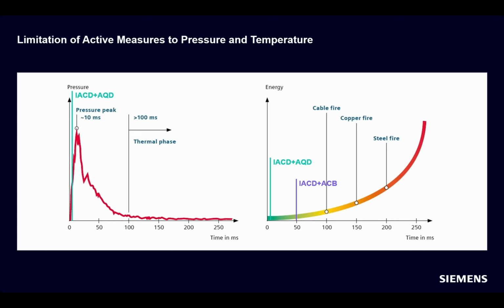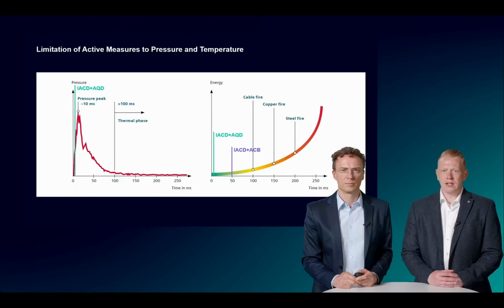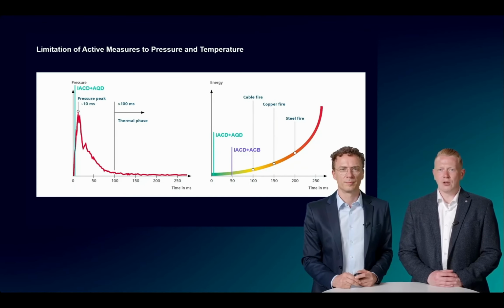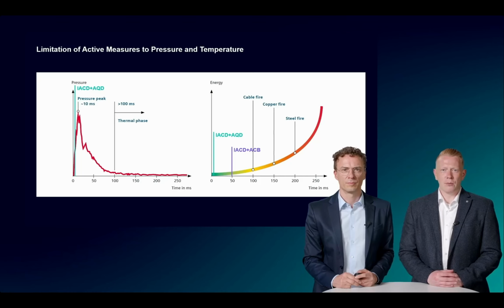The difference in comparison to public distribution systems is that here in industrial systems, like the ones shown here, the distances are normally shorter. So we are within one plant, in the chemical plant or refinery. Distances are shorter, and we normally have a lot of motors involved here. We see that there is an increased risk of fire, beginning in the range of temperature rise from approximately 100 milliseconds. Due to the exponential increase, the risk of damage is also increasing with every millisecond. But the main question for protection is: do we have meshes or is this a radial system? That was the pressure curve, the system structure.